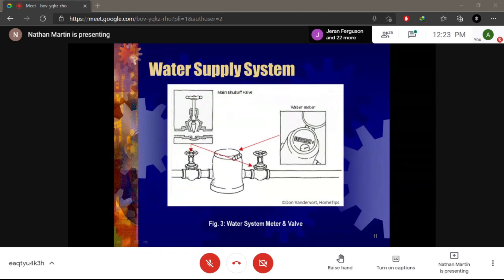Sometimes they just install it straight from the shutoff valve to your meter, and then from your meter to the other shutoff valve. So it depends, guys, on the plumber and the configuration they want to use. I prefer to use, and most plumbers will prefer to use, the unions, but because of the cost, persons will not tend to want to buy them, right?